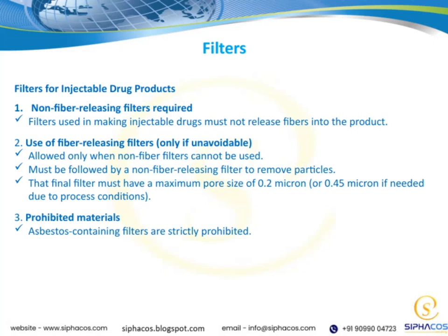When it comes to filters for injectable drug products, the key point is that non-fiber-releasing filters are required. This means that during the manufacturing process, the filters used must not shed fibers into the final product, as that could pose contamination risks. However, there are situations where fiber-releasing filters might be unavoidable. In such cases, their use is only permissible if no suitable non-fiber filter is available. Even then, it's crucial to follow the fiber-releasing filter with a non-fiber-releasing filter to ensure any particles are effectively removed.